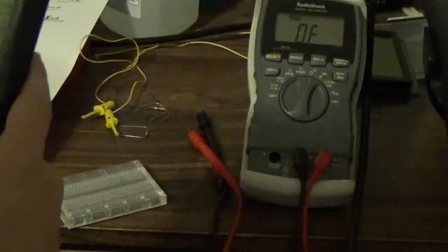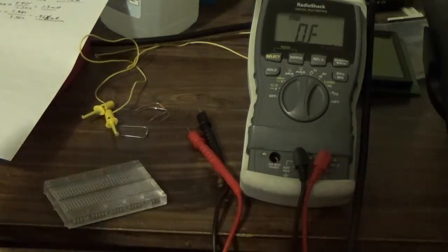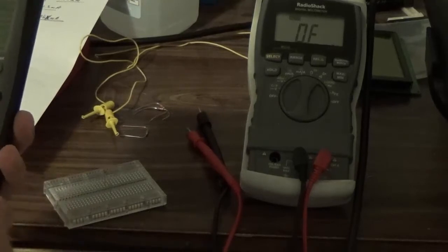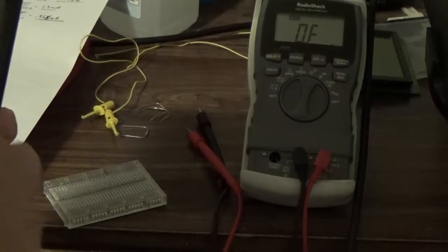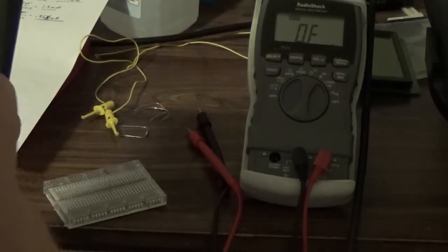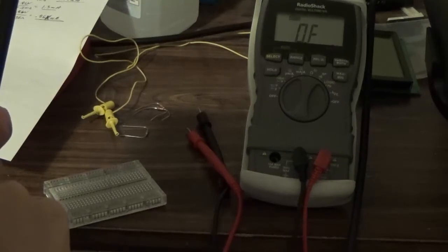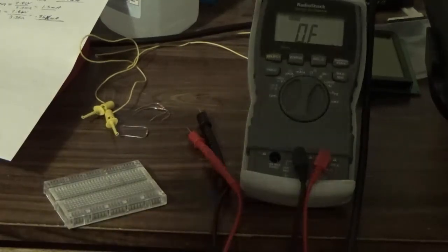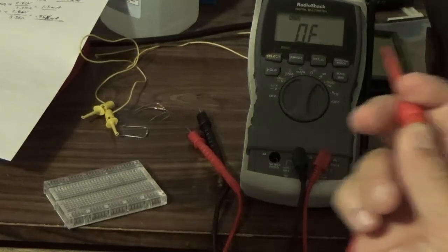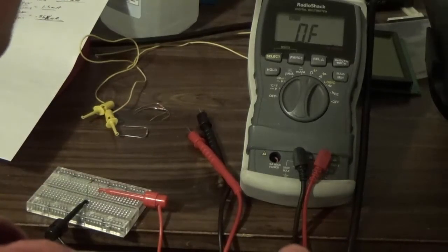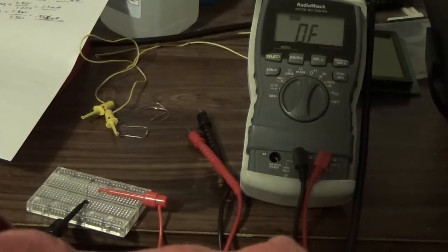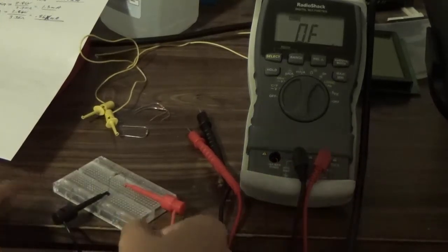So that voltage should be, let's figure out what it is, and I will try to drive it to that point, if I can even drive it to that point. Let's see, 300 times 0.25, and then take the square root of that value. 8.6. So what we're seeing is around 9 volts, this thing should give up the ghost. So let's see if that happens. We should see right around 9 volts.